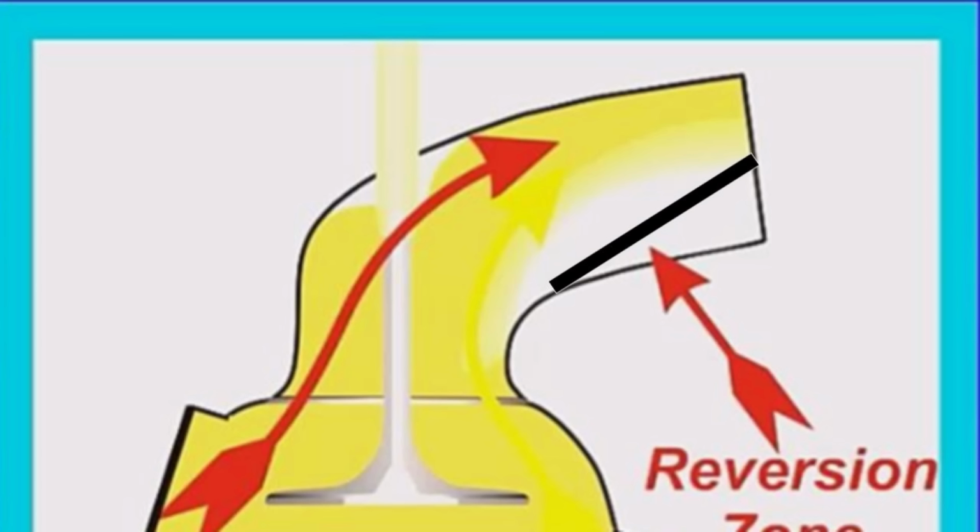But if we analyze the discharge coefficient of the port flowing backwards, then once the valve gets off the seat any substantial amount, the flow backwards is absolutely terrible. So what we've done is make a valve which has no moving parts, not 100% efficient, but no moving parts, and serves our purpose. But there is one problem.